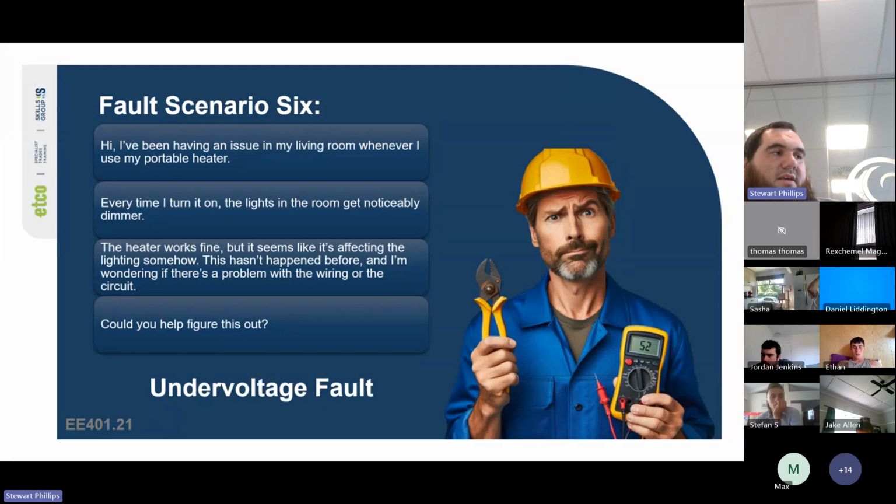So yeah, that's one of the best signs that either there's an undervoltage problem, a broken neutral, or that the phase connection at the pole isn't as good. I've had that a couple times as well, although the linesman never wanted to admit that I might be right.